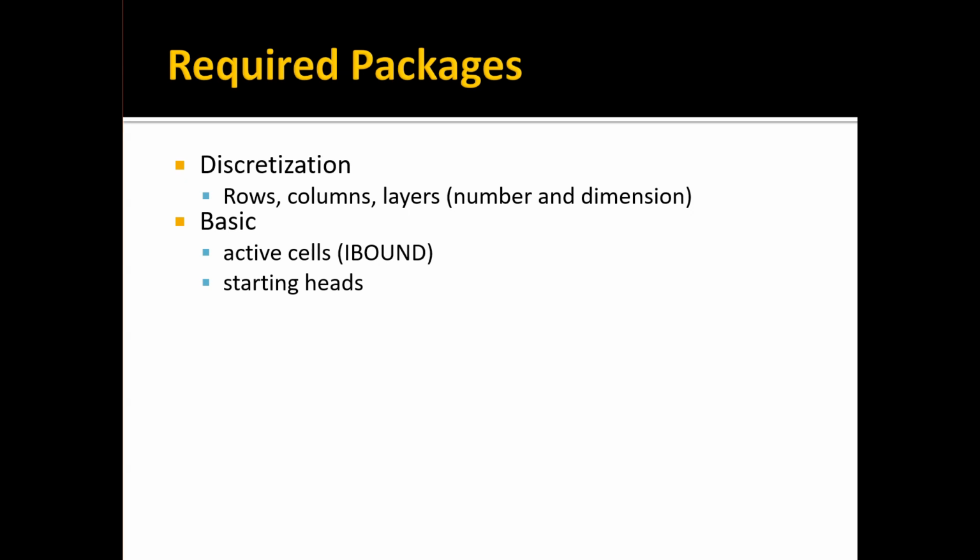There's also a basic package, as it's called, and this is where you define the active and inactive regions of your model. And we're going to have an example of that in the next slide. You also input the starting heads. Modflow uses an iterative solver, and so you have to give it an initial guess for each cell.